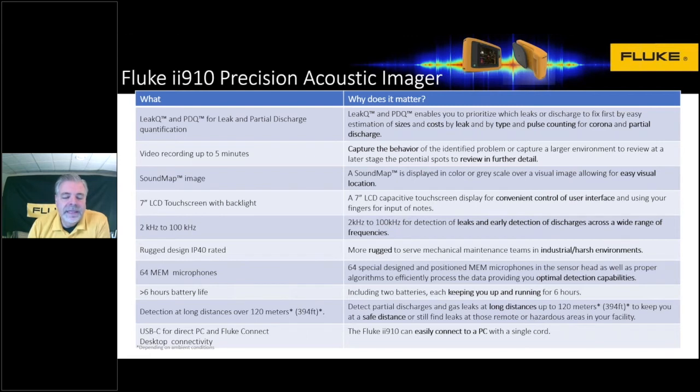capture the PD events from a PD count point of view, which I understand other companies have been doing for a while, and we can measure the distance to that PD event. We can do video recording again for 5 minutes. The sound map image is the same.